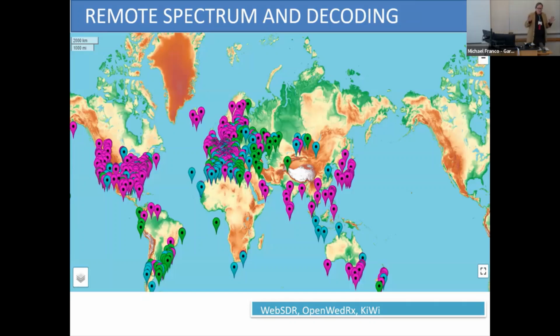So he's got all these protocols that go down very low. Now the Whisper protocol works at 10 hertz. So he's taken Shannon and has knocked it down to 10 hertz. That's in conjunction with some basic hardware as well. Right, but no, he's using a PC. So he's doing all the software defined radio and bandpass filtering in software. He's using a standard PC or a Linux system, running all this stuff, so you can experiment with it.